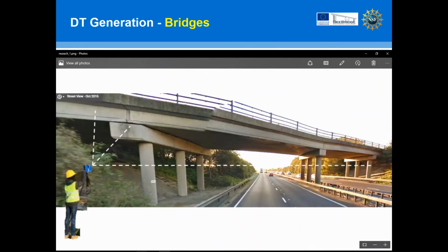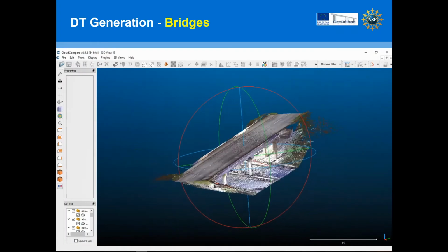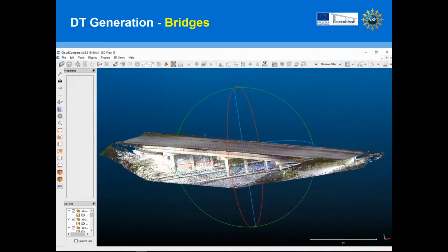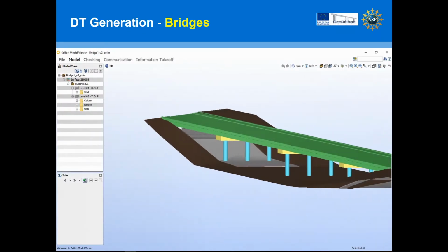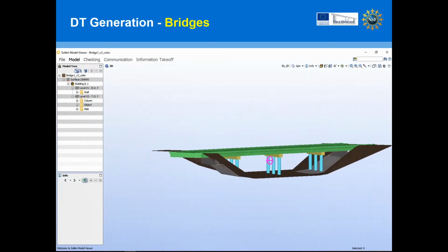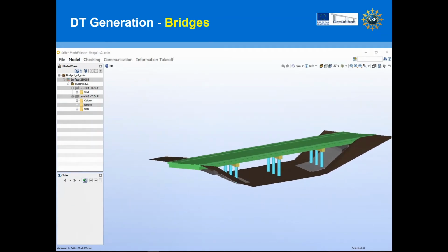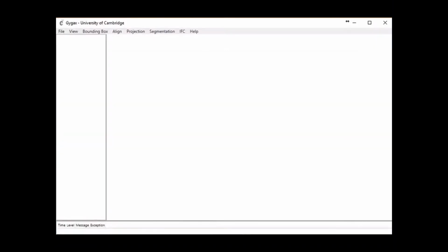So where we stand today, remember I mentioned before top down and bottom up. We've done bridges quite effectively using top down methods. In fact, quite deterministic with very little machine learning element in there. By going to the entire structure, segmenting the deck, because we know to expect it. This is asset specific rather than asset invariant. And then knowing exactly where to expect the pier caps, exactly where to expect the columns and so on. We look for them in those places, find them, and put them in the model. And this is very powerful because